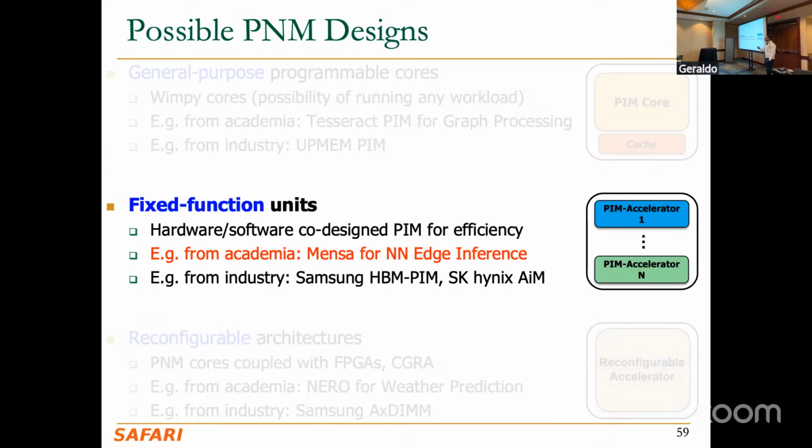In contrast, if you have to do the same thing on the host processor without UPMEM, the premise is that you would move the input and output data from main memory to the CPU, plus those intermediate data would also be moving back and forth between CPU and main memory. So basically what we're eliminating is intermediate data movement here.